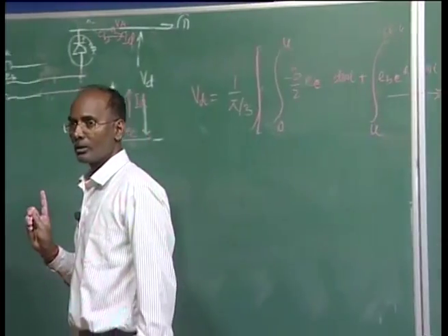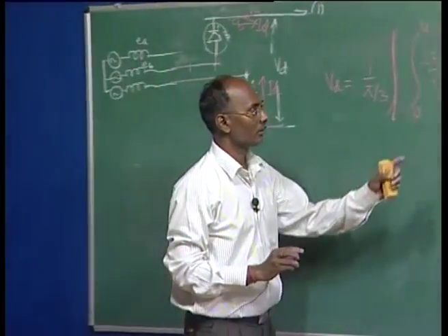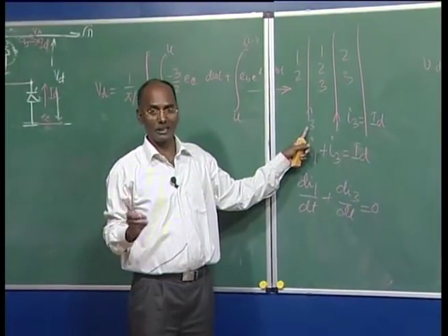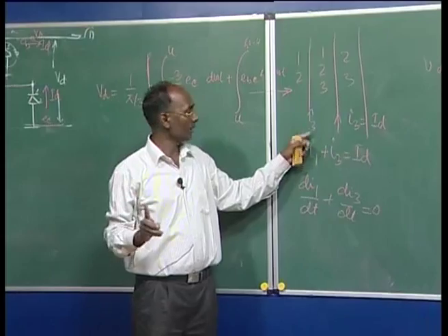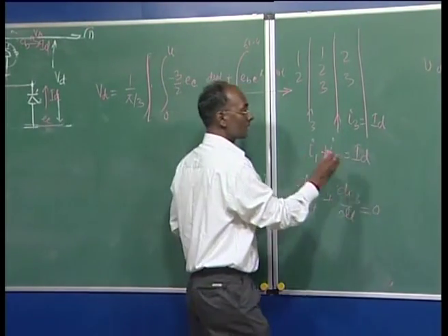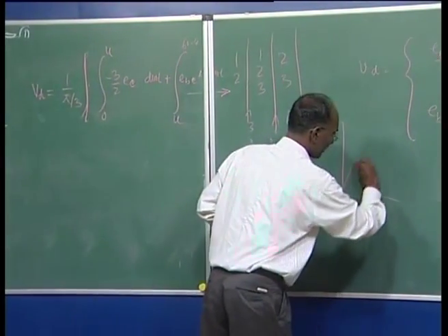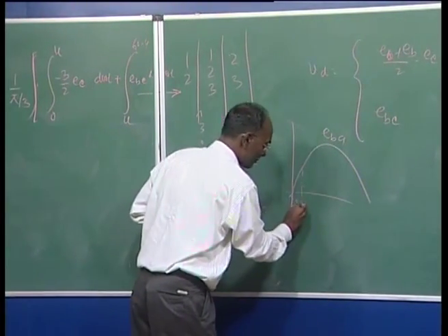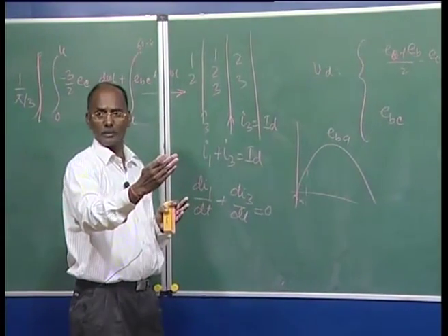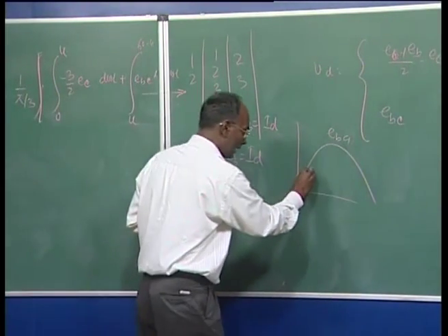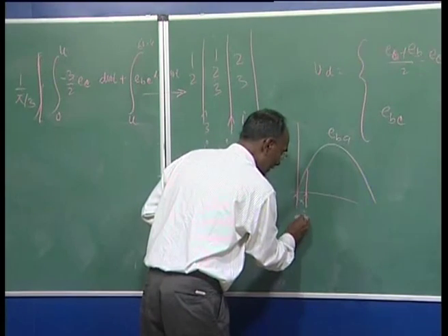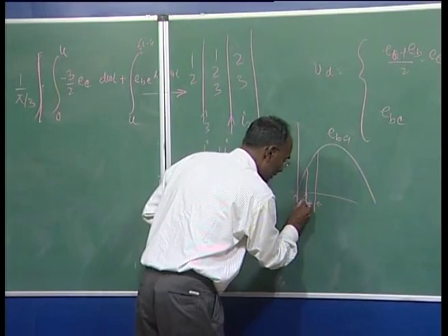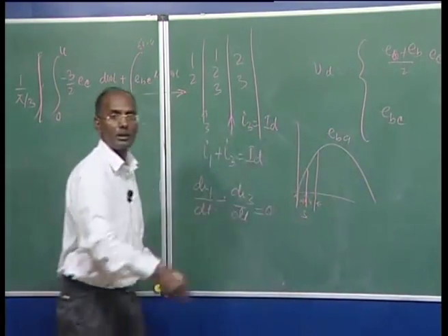One thing here: we are starting, that is once valve 3 is taking place, at this point we are assuming that there is no delay, which means u is equal to 0. But here, as a commutation voltage, once it is starting, as I said, whatever the voltage E_BA is, valve 3 you can start here, or you can start with some alpha degree delay. So, once valve 3 is fired, the commutation will occur during the u period, and for the remaining period the u will be over.